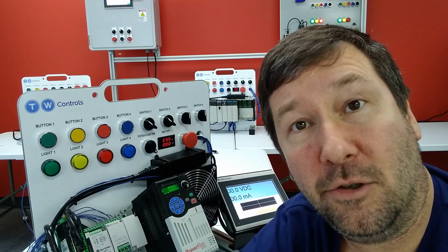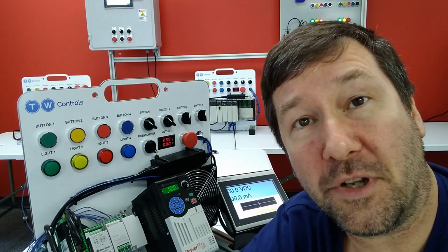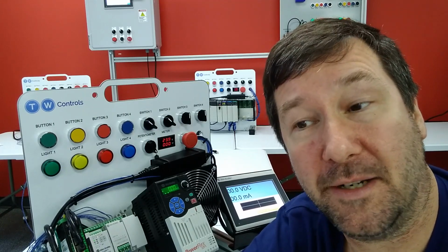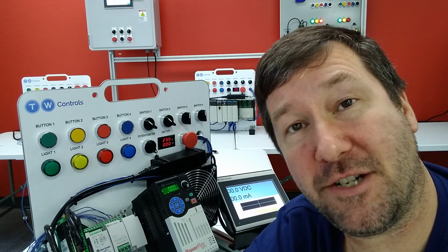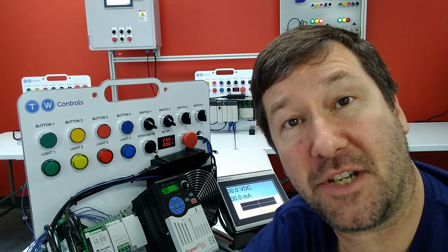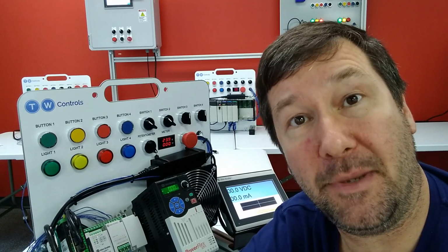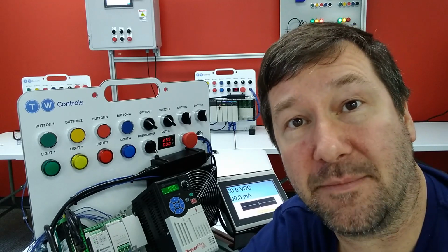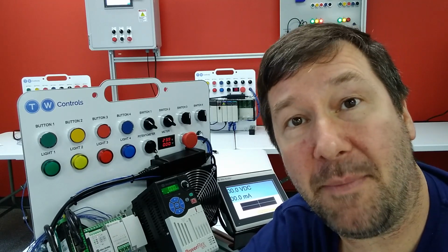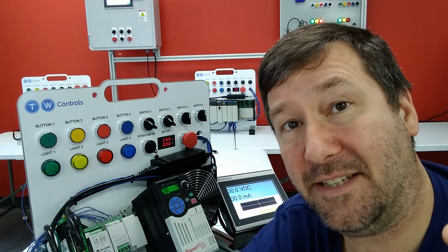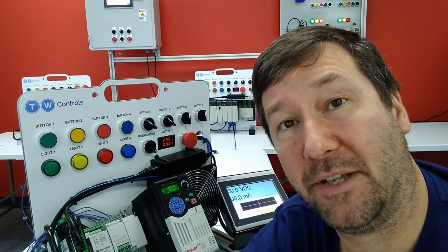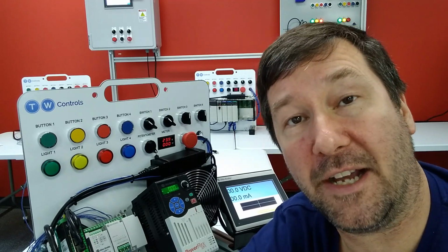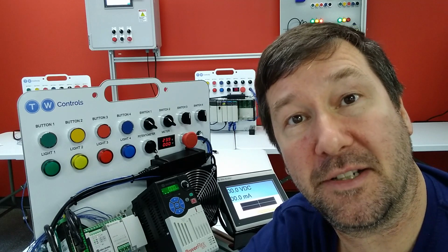The current 2-wire loop and the current source are both 4 to 20 milliamp signals. So let's start by distinguishing when you need which one. Let's say you want to simulate something such as a pressure sensor that only has 2 wires coming out of it. Well, in that case, it will be a 2-wire current loop. On the other hand, if you have a pH transmitter that is externally powered, maybe by 120 volt, and then it has a plus milliamp and a minus milliamp terminal completely separate from that, then it is probably going to be a 4-wire device, which we would use the current source mode to simulate.